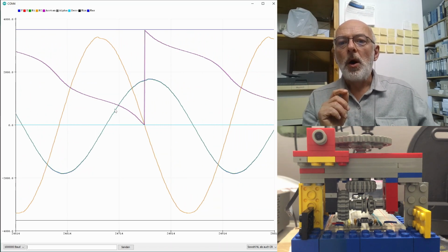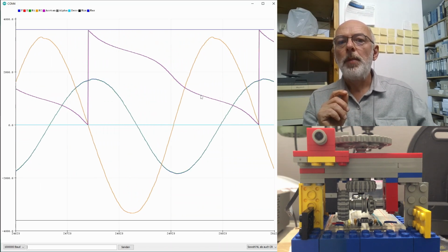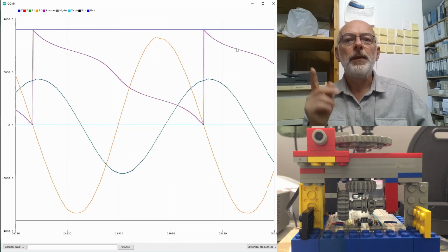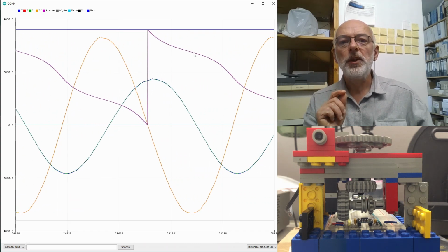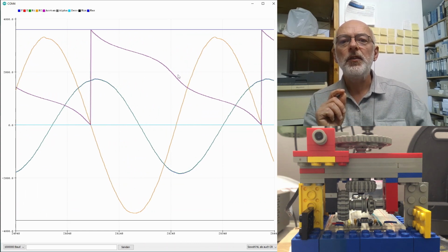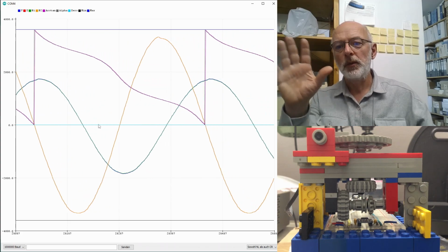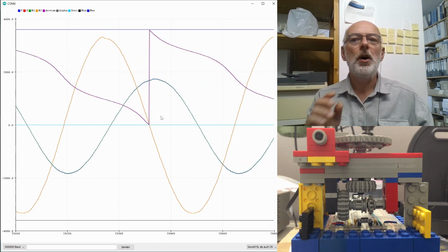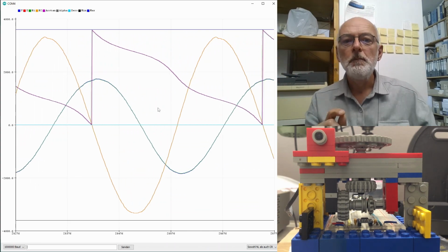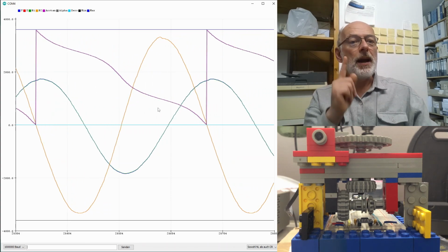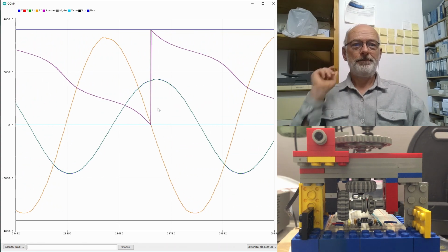Anyway, our angle readings, both the one we calculate and the one returned from the chip, are quite distorted because of the discrepancy between the amplitudes of our two signals. But there is a cure for that.